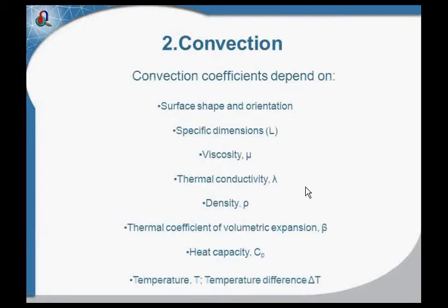Convection coefficient depends on many properties, many things. It depends on the surface, shape and orientation, and a lot of properties of the medium. For example, viscosity. In our case, it's the viscosity of the air, thermal conductivity, density, coefficient of volumetric expansion, heat capacity, temperature difference.